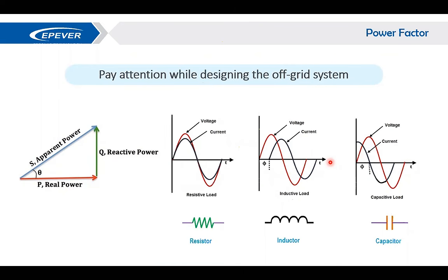And if the power factor is less than 1, you have to supply more current to the load for a given amount of power. And as you can see, capacitors have the opposite effect and can compensate for the inductive effect. And that's the reason that some industrial sites or even some buildings have large banks of capacitors. That's the usage of a capacitive bank: to bring the power factor up to 1 while consuming the same power.